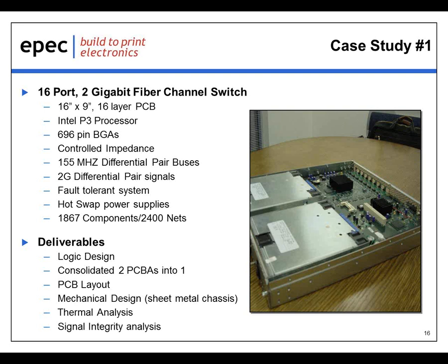The approach we took was to redesign, combine the 2 boards, and that drove mechanical changes. So we implemented mechanical changes in the chassis you see here, and it drove signal integrity analysis to verify that the signal and data rates, signal and data quality were maintained or better than the original product.